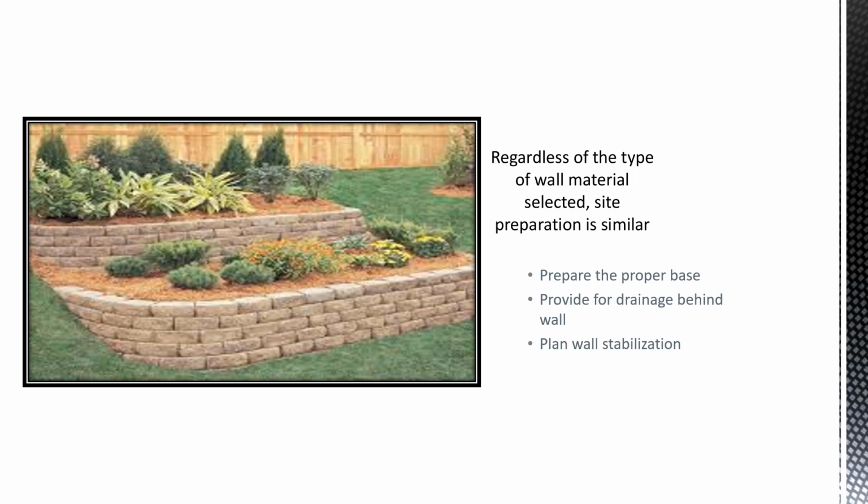We're going to continue to see it with the types of people out there that are installing these walls. But the solution to it, guys, is to get an engineer. You have to have an engineer. There's no ifs, ands, or buts about it. When it gets over 4 feet in the state of North Carolina, you got to have it engineered anyway. So, have an engineer that you can call and actually help you out with these situations.